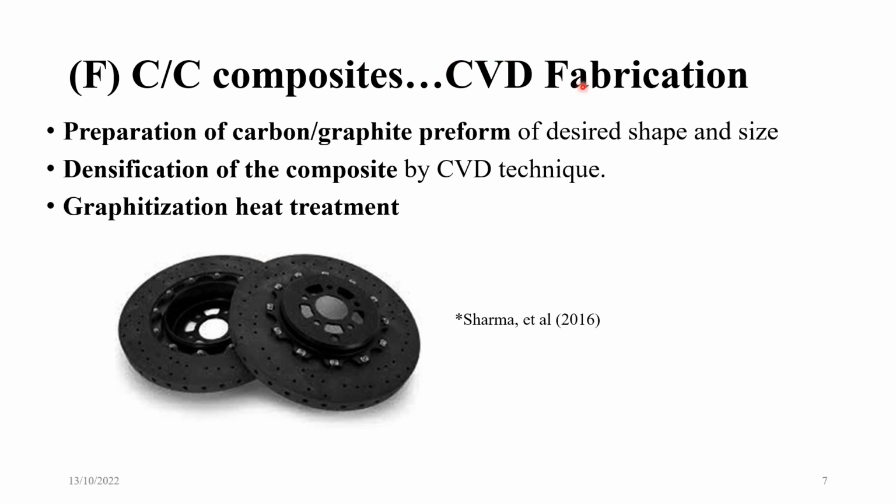Next, with CVD fabrication, chemical vapor deposition, preparation of carbon or graphite preform, this step remains the same. Densification is required, but here you are repeating the CVD cycle, and graphitization heat treatment. We can see two brake discs have been shown made of carbon-carbon composites.